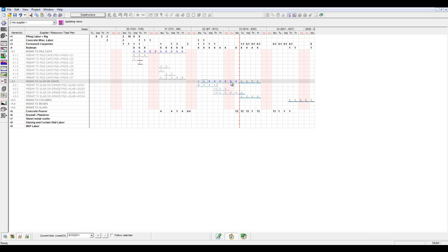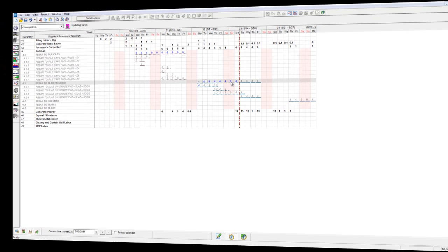It's important to remind you that you must enter crew actuals on a weekly basis. It's suggested that you do this just after entering the date actuals. Further, we need to enter in the actual resources, even if they look right; they must be locked in place and turned blue. Again, this directly impacts the forecasting mechanism of Vico Schedule Planner.